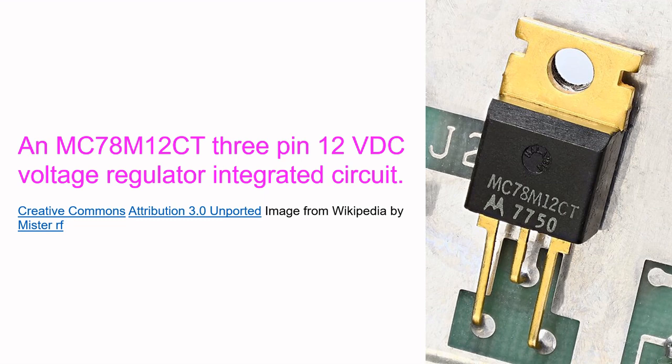Current fallback is a current limiting feature so that when the load attempts to draw more current from the supply, fallback reduces both the output voltage and current well below the normal operating limits. When there is a short circuit, current is typically limited to a small fraction of the maximum current by the fallback mechanism. That reduces the risk of fire and damage due to heat.